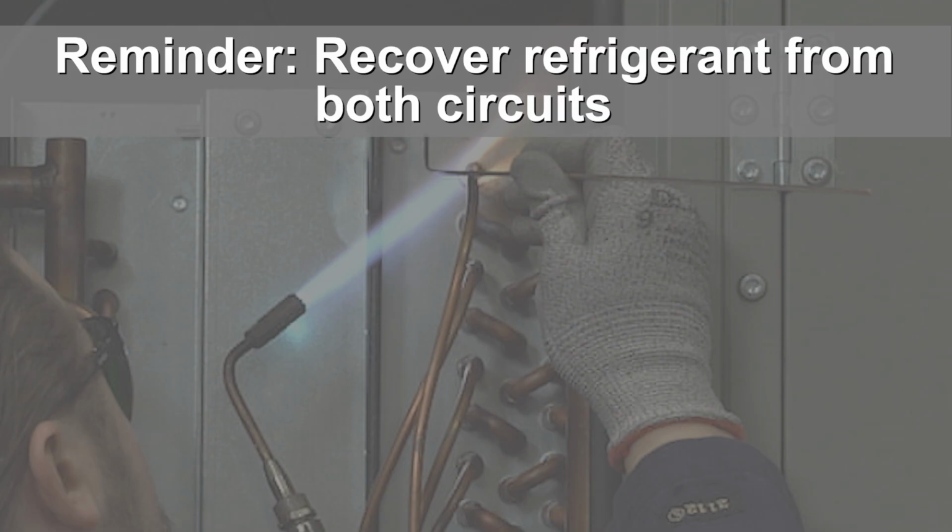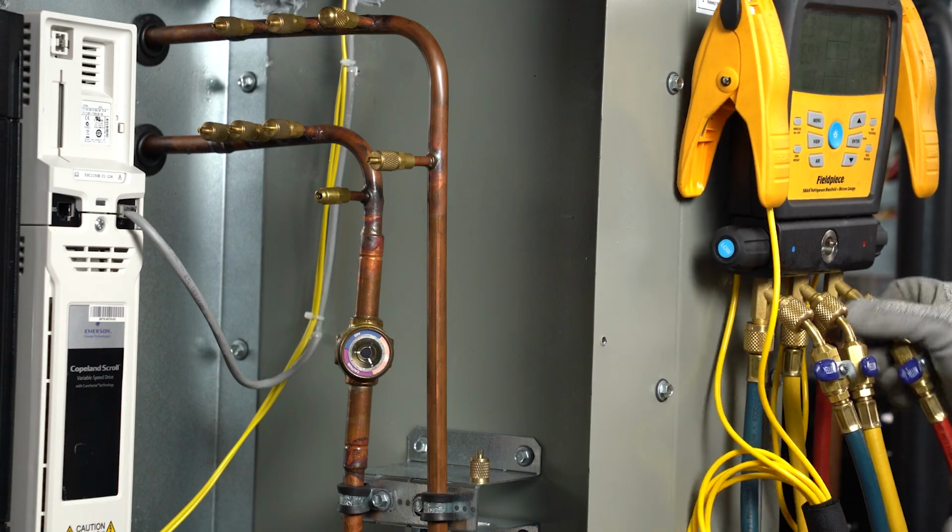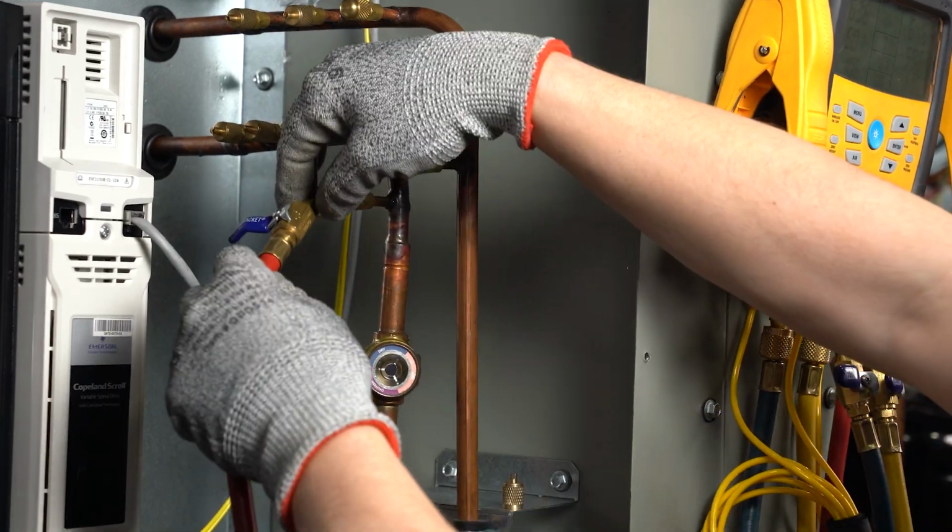As a safety reminder, recover both circuits if brazing on an interlaced evaporator coil. To recover refrigerant from a circuit, connect a manifold gauge set to the liquid and suction line.